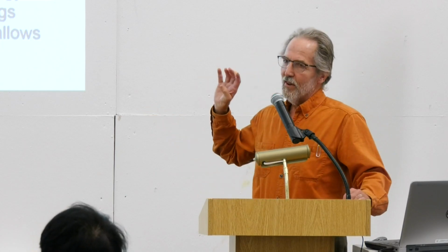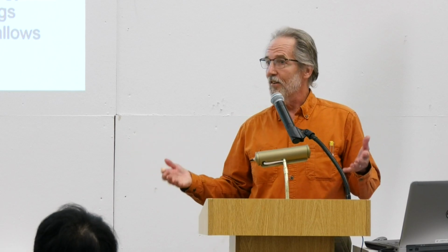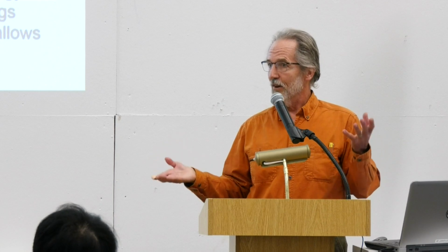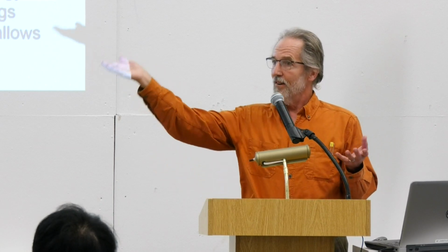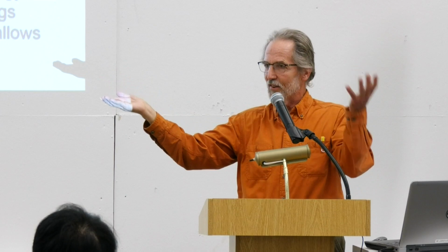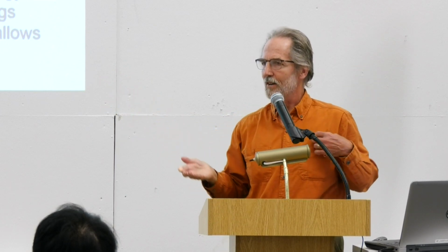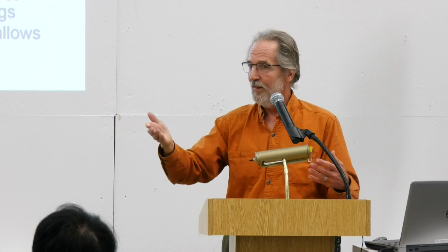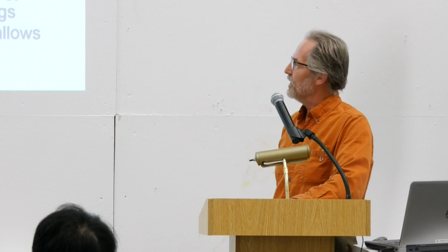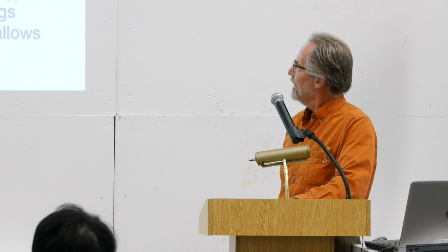That's why most zero net energy buildings have not had batteries. In a way, I say to people, zero net energy is an abstraction. You're basically saying, I'm going to take this summer surplus and use it to balance this winter shortcoming. But you can't really store that summer energy until the winter, even if you have batteries. So I want you to realize that most buildings actually still have a grid connection.